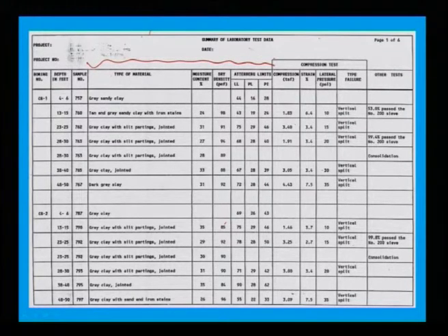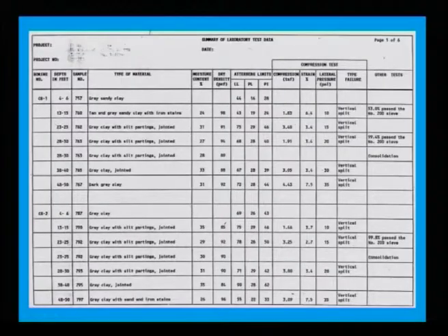This is all about classification data. Then your real engineering data, engineering property or strength parameters, C and phi. How do you get these? If you look here, compression test means either you go for a triaxial test or a direct shear test, from where you get the compression and the strain. That means at this strain, this is your failure load you are getting.